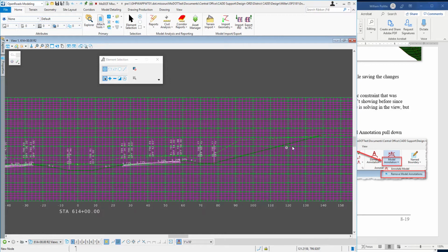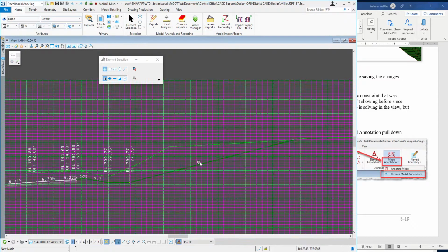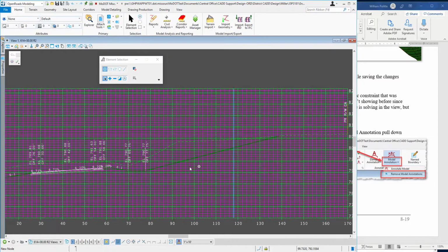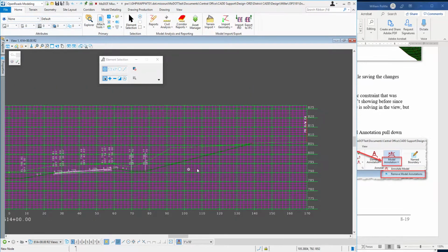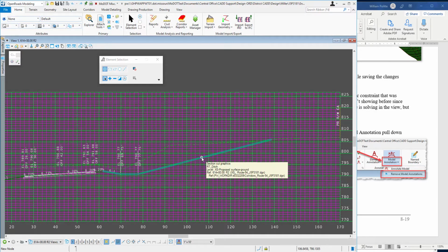Okay, so you can see out here on the right side, here's my ditch. My slope's been brought in. There's no label on it. Now before, that slope was going way out, like it describes in the manual. It was going so far out that it didn't show up on the sheet. So it was on the grid. So it was out here. When it's like that, it won't label. Okay, so the point has to be in play for it to label. So now it is, but again, annotation is not automatic. So let's go back to the manual.